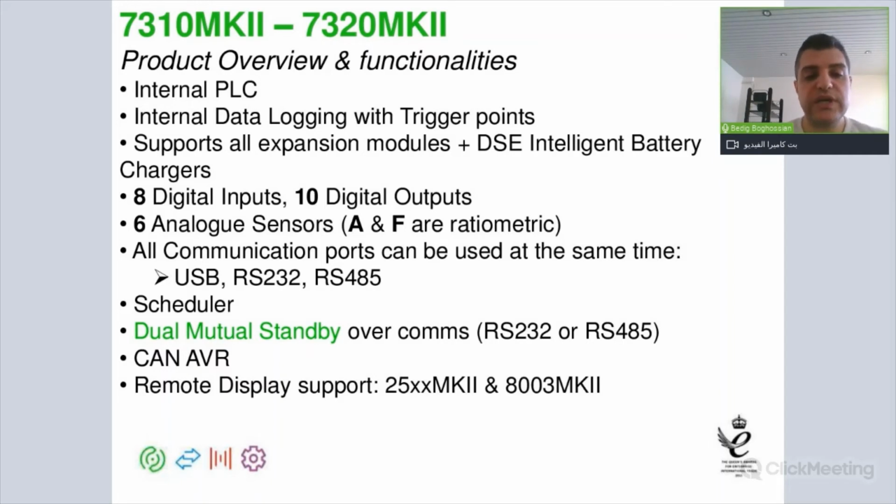It does support communication ports. So within your application, you may have a BMS reading requirement, where the end customer wants to monitor the genset instrumentation via Modbus. We support that over the RS-232 and RS-485. This controller, the 73 Mark II, doesn't have a TCP port. So if you need a TCP port, we are able to provide that on the 73 by adding another accessory, which we will look at on the next slide.